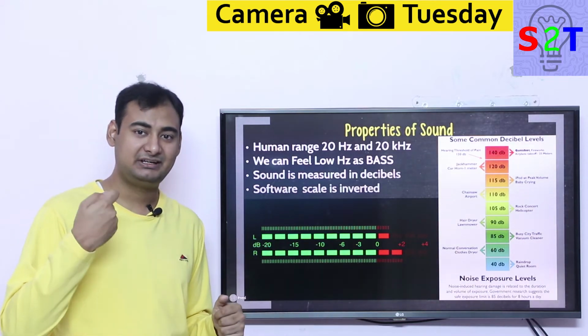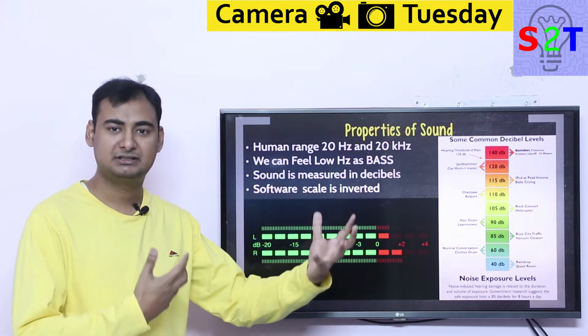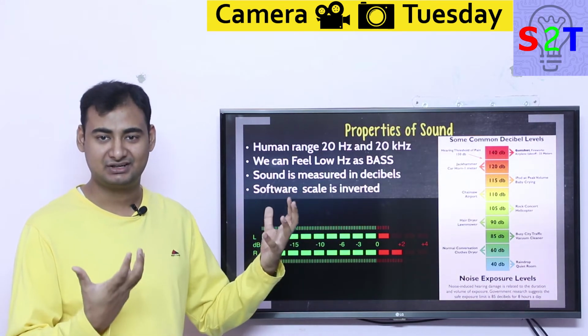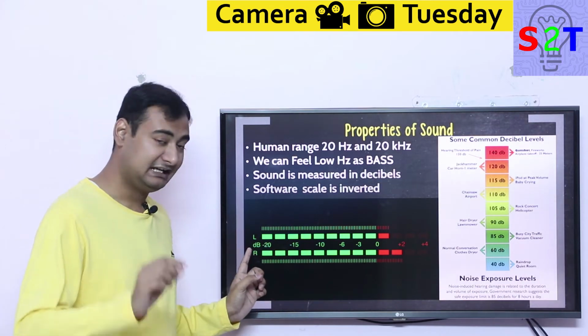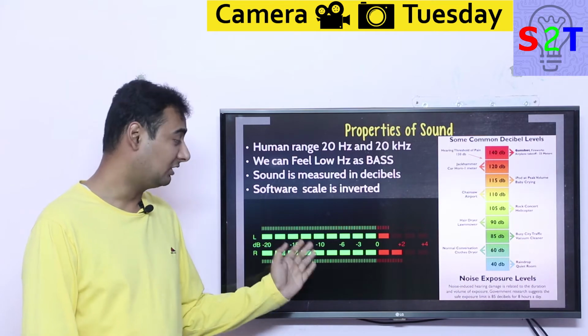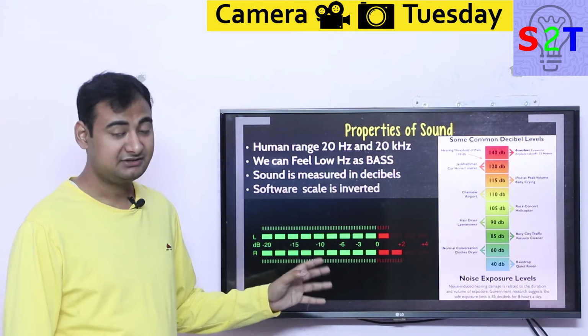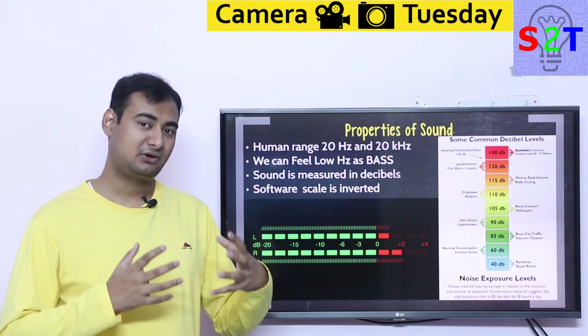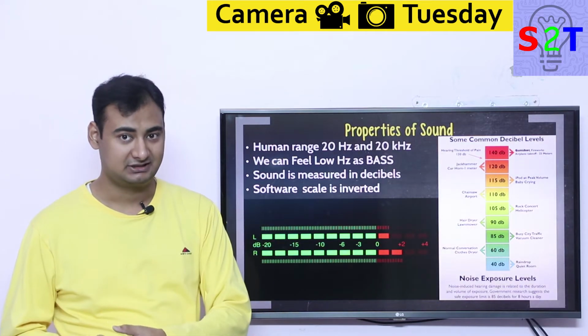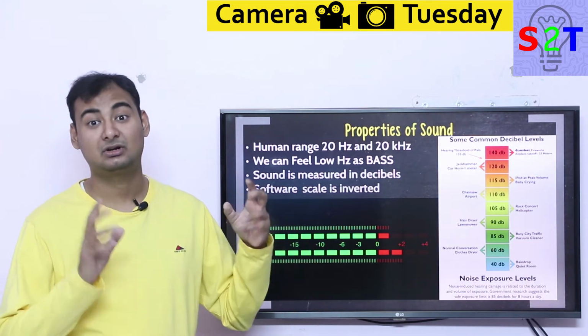So that's why, even though your TV volume was low, and the signal was -20, you're having a conversation and enjoying it. But when the advertisement happens, the signal from the advertisement department is basically 10 dB higher, sometimes as high as -6. That will make your TV scream as loud as it can at the volume it already has. So it's not like your volume went up, it's simply because it's receiving a signal that's much more hot.